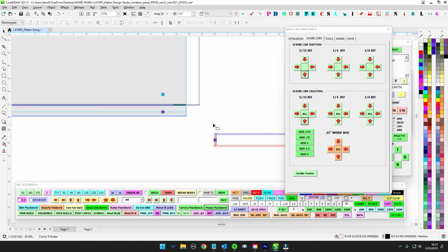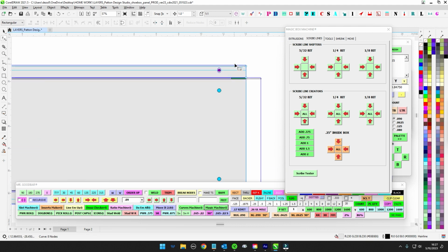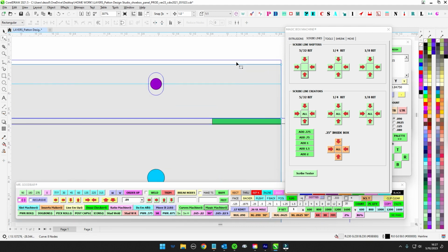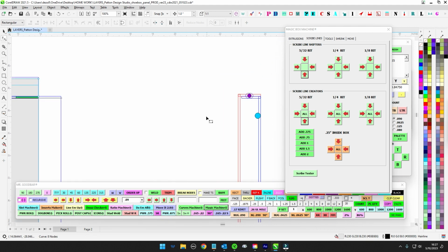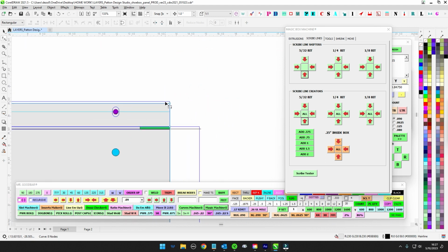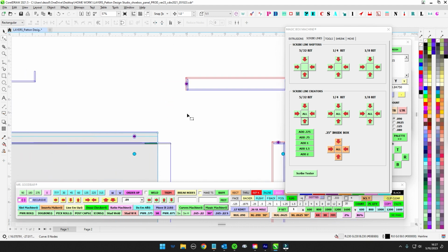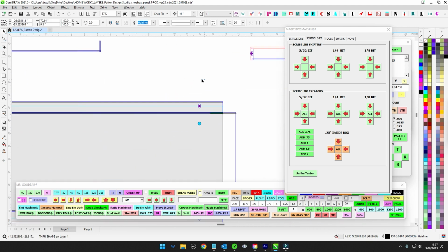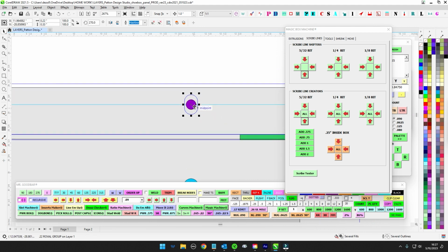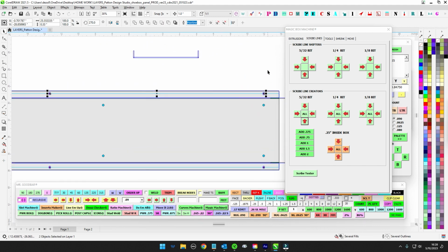There we go. So now when fabrication clamps this and bends it, this will regrow to that point, and then that will then become this true size. Otherwise, it would grow 1/16 and it won't fit. Well, this would be right at, but anyway, you have to allow for that. Now, the other thing you have to allow for is the position of this will then shift 1/16 unless you account for it. So you have to account for the hardware moving as well.